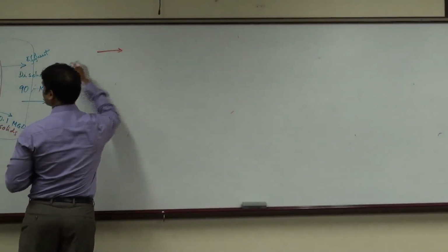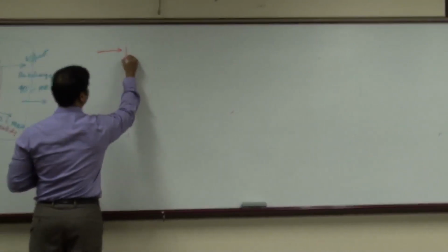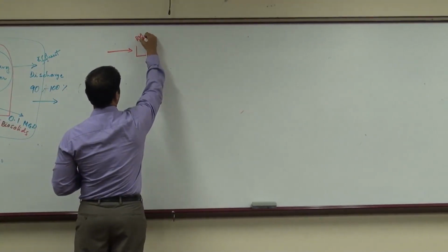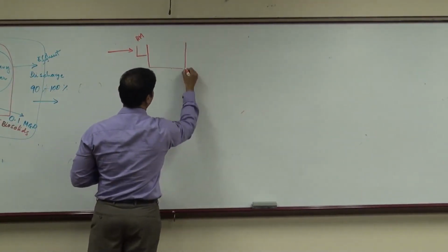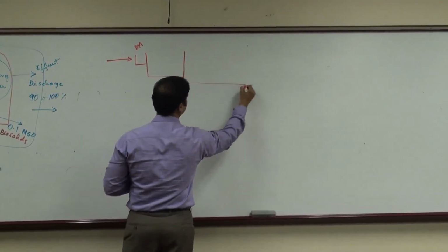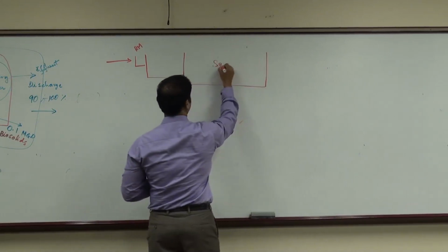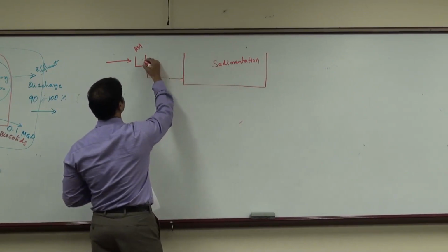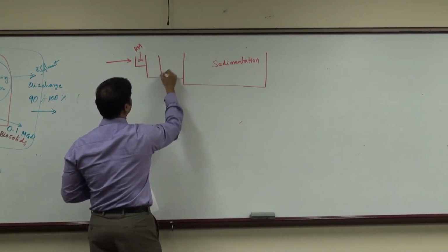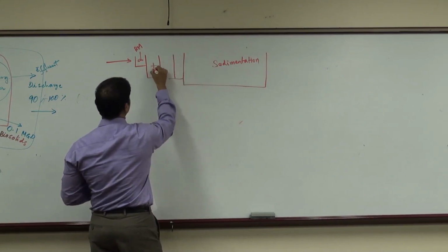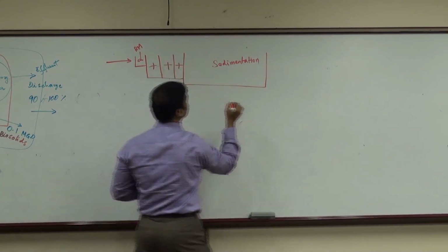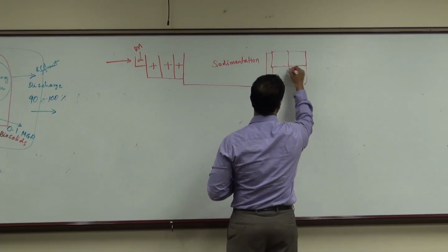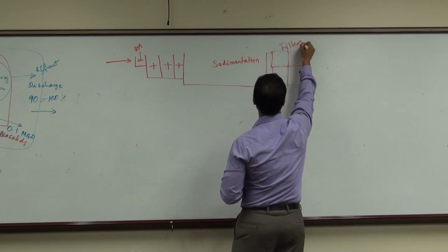So now I just show you this wastewater treatment plant. Now this is going to be water treatment plant. You have rapid mixing process (RM), and then you have a flocculation basin, and then you have a sedimentation basin. If you remember this train, I think I drew it a couple times in your class. This is a flocculation. When you have filters, finally, these are filters.